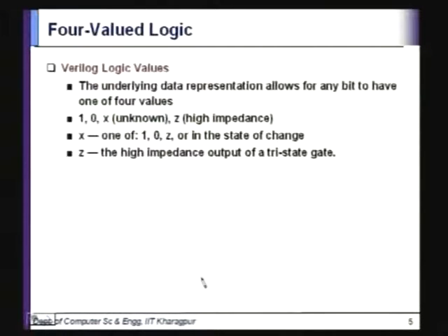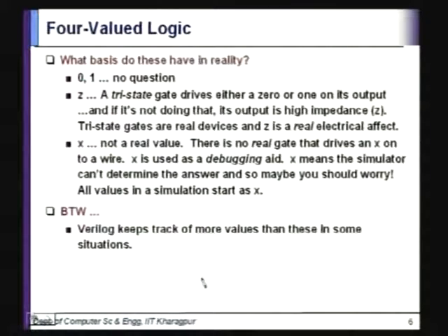So what are the other outputs that feed into the bus going to be in? They are going to be tri-stated, right. So all except the current driver will be tri-stated, right. That is why tri-state is a very important component, and we cannot simply ignore tri-state.